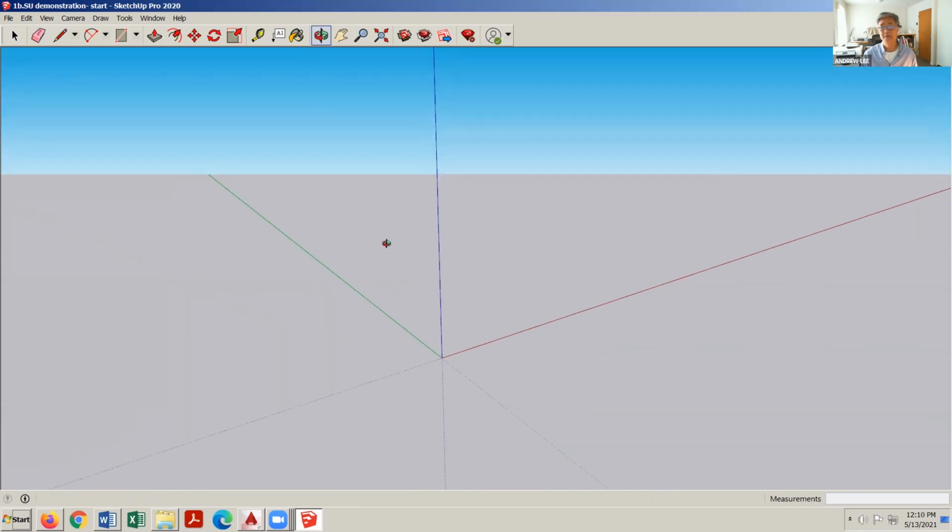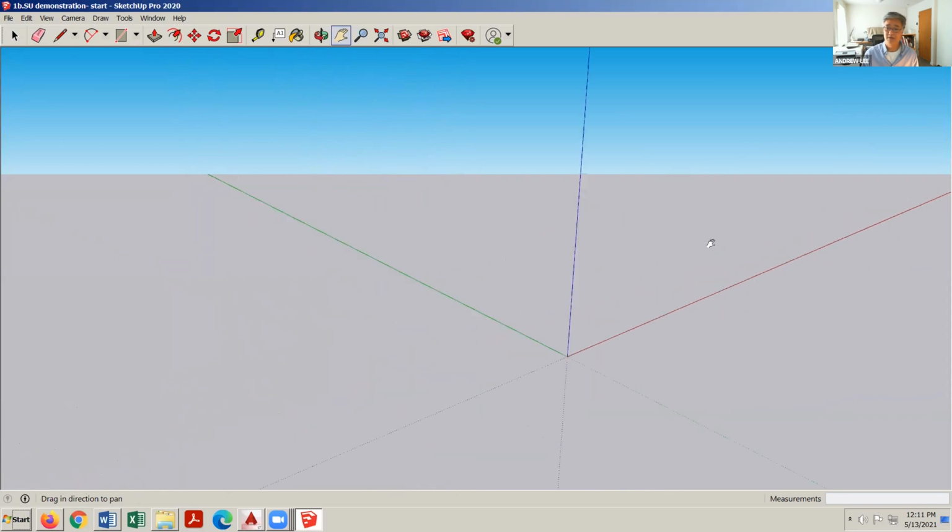the scene. The second way to move around in SketchUp, in the SketchUp world, is pan, which operates just like it does in AutoCAD. You can see there's that little hand there, and it says pan. My shortcut is H. You can see your arrow turns into a little hand. And again, you press down on your mouse key and then scroll around with your mouse,